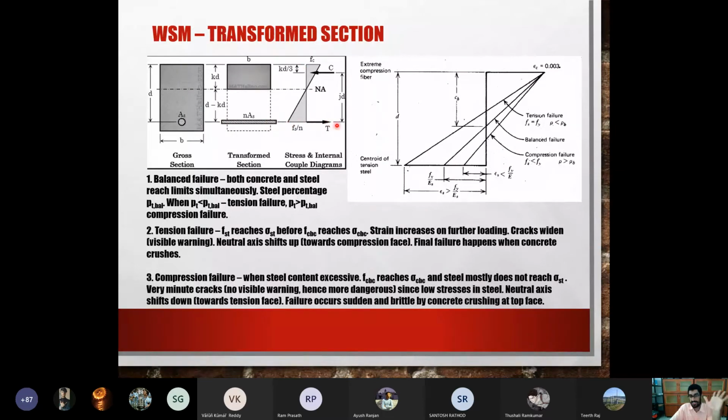This is tensile stress. This tensile stress will act where the reinforcement is, because only the reinforcement is assumed to take the tensile stress. Concrete is not assumed to take any tensile stress. So the distance between these two opposite and parallel forces is given by JD.